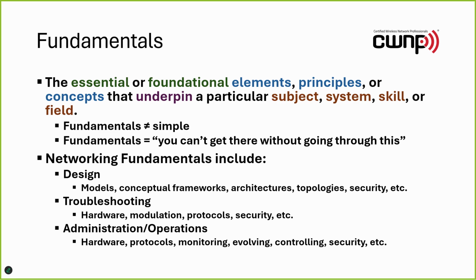So, for example, if you are a farther distance away from the Wi-Fi access point, you will be using a lower modulation rate. That's why you have, in part, a lower data rate. And so understanding that simpler modulation can be demodulated with poorer signals explains to you why it is that as you get a weaker and weaker signal, you get a lower and lower data rate. It's because you're using lower and lower modulation rates, which are simpler than the more complex modulations that require a better signal or a higher signal strength or signal quality.